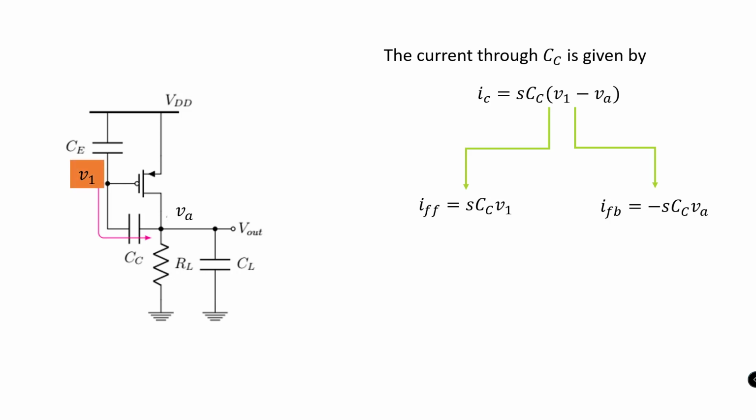Also note that when the node potential V1 is excited, it produces a small signal current at the drain of M9. When you look closer, you could observe that the feed-forward current and the drain current are functions of V1, and the sum of both these currents is what defines the output current I0. And when this I0 flows through the output impedance, it results in an output voltage V0.